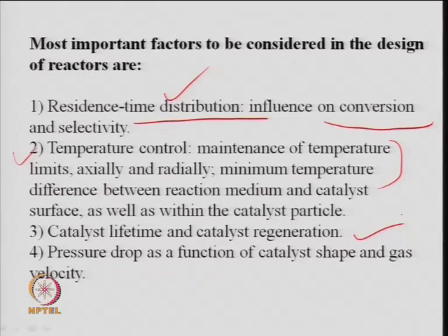Pressure drop as a function of catalyst shape and gas velocity. As I discussed, in the fixed bed reactor there is the calculation of pressure drop, and also fluidized bed reactor pressure drop. So, the Kozeny-Carman equation and the Blake-Plummer equation you must have read in fluid mechanics. So, you know how to calculate this.